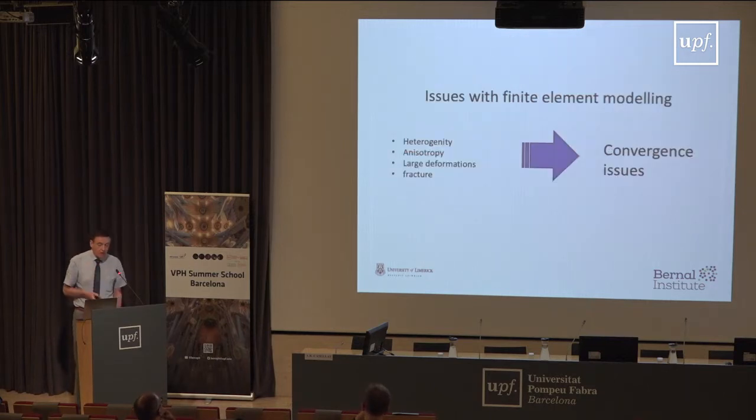Now, if we look at what happens when we start on finite element analysis of specific organs, such as the intervertebral disc, my experience, and usually that is not very much reported in the literature, is that quite often, because of the complexity of what we are studying, including the heterogeneity of the domain, the anisotropy, very large deformations, discontinuities like contact or fracture, people using standard tools such as Abaqus or ANSYS or whatever, they get convergence issues.